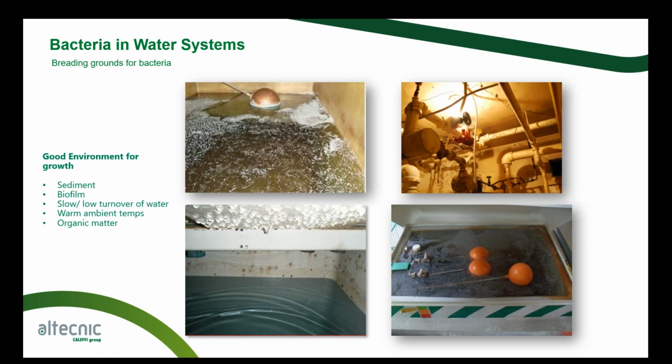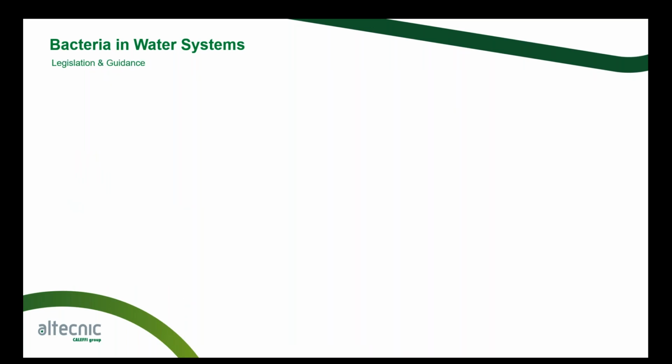And the cold water is soon going to increase in temperature, and we're going to start to enter some really dangerous ranges for bacteria. And of course, there's a lot of the way that pipe work has been reduced as well. You're going to get sort of low flow areas of pipe work, etc. So it's very important we take into account all of these things when we're looking at trying to prevent the environments for growth for bacteria.